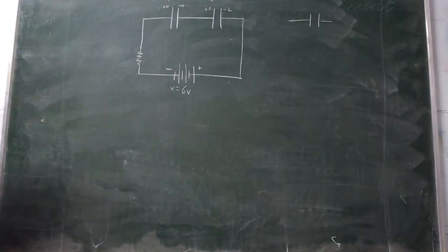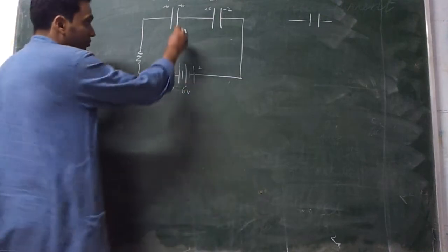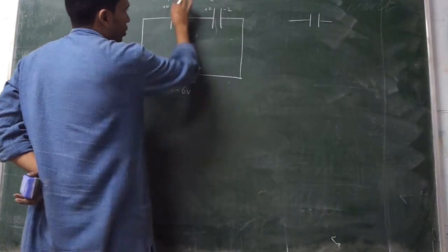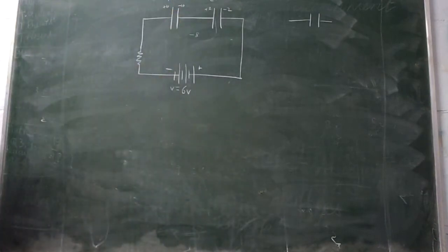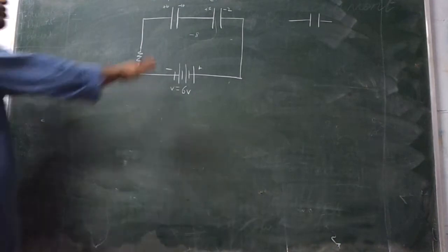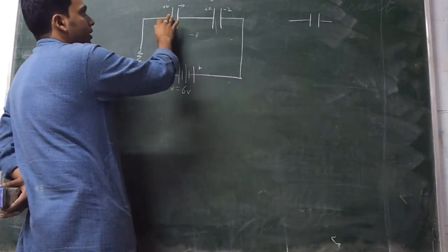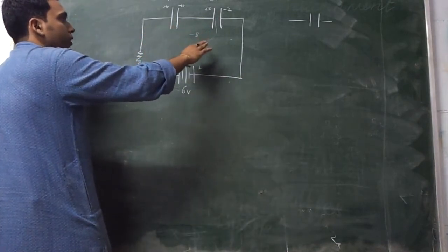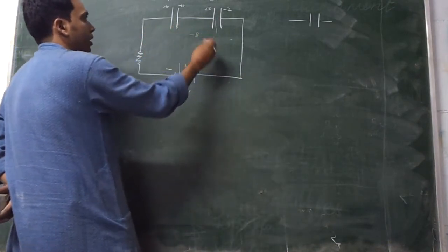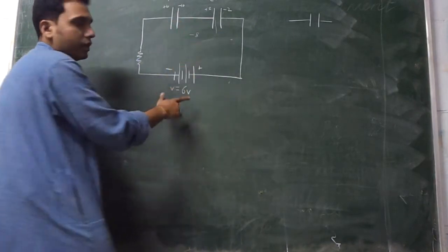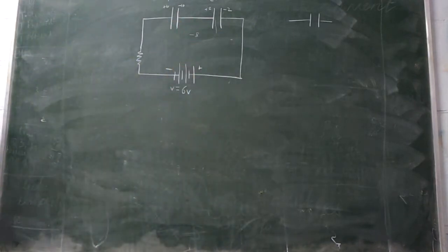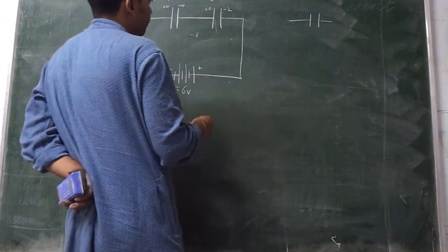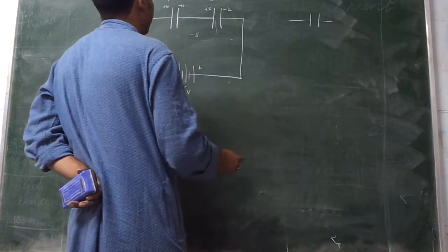So what is basically going to happen is, this minus 10 plus 2, there is a minus 8 coulomb trapped over here. That will go nowhere. That minus 8 has to be over there. So this and that will redistribute, some charge will go from here to there or there to here, in such a way that minus 8 has to be over here, and the total voltage drop has to be 6 volt. You can solve it in many ways, but we'll solve it the way I am showing you right now, and later we'll discuss other ways also.